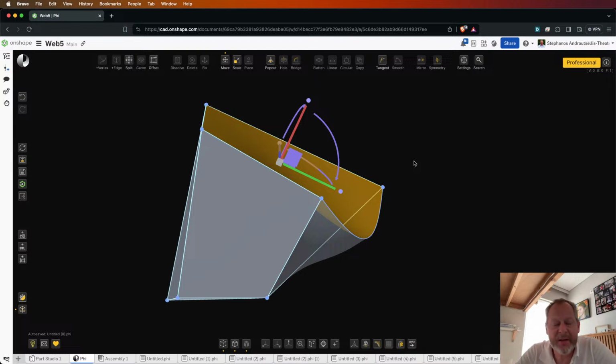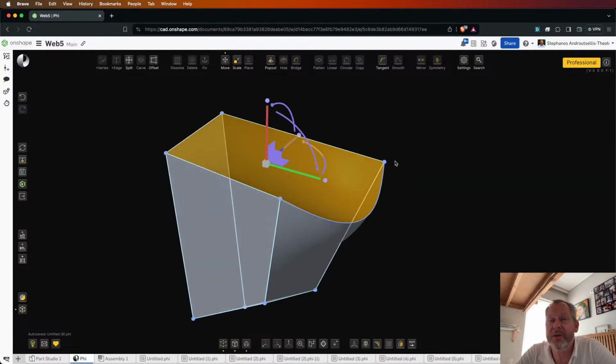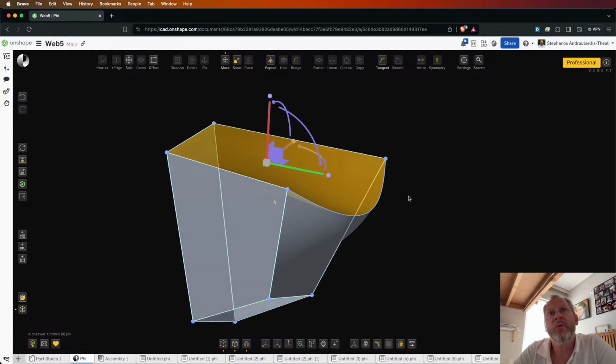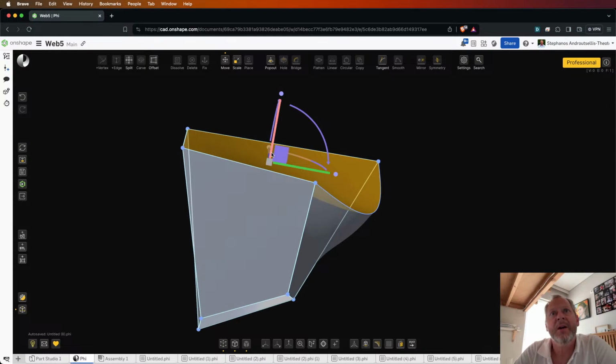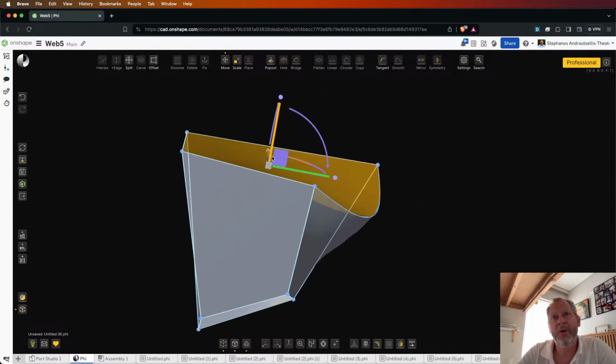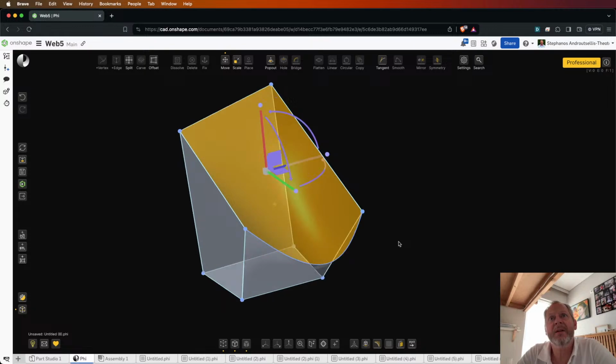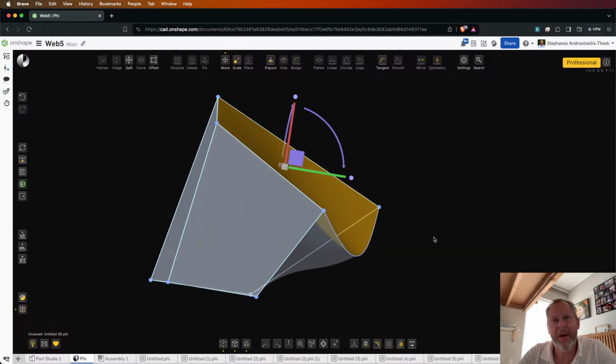Now in this case the selected element is just one face and it's not a flat face, but we calculate with adequate precision an average normal to this face and we place the manipulator along that, which is convenient because now you can pull along the normal to this face. If you want to go back to a global positioning, you hit the G shortcut and you're back into the global coordinate system. So L and G help you switch between these two.